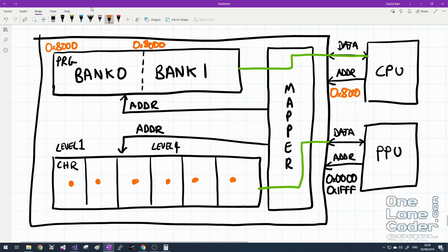It also contains a few other bits and pieces that the NES needs to configure its hardware. So just a quick recap, the CPU configures the mapper and the mapper translates the addresses from either the CPU bus or the PPU bus in order to read and write data to the memories contained on the cartridge. And just an aside, this is why there were really no loading times on the older consoles. Today we expect games to load all of the graphics for level 1 and then move on and it loads all of the graphics for level 2, etc, etc.